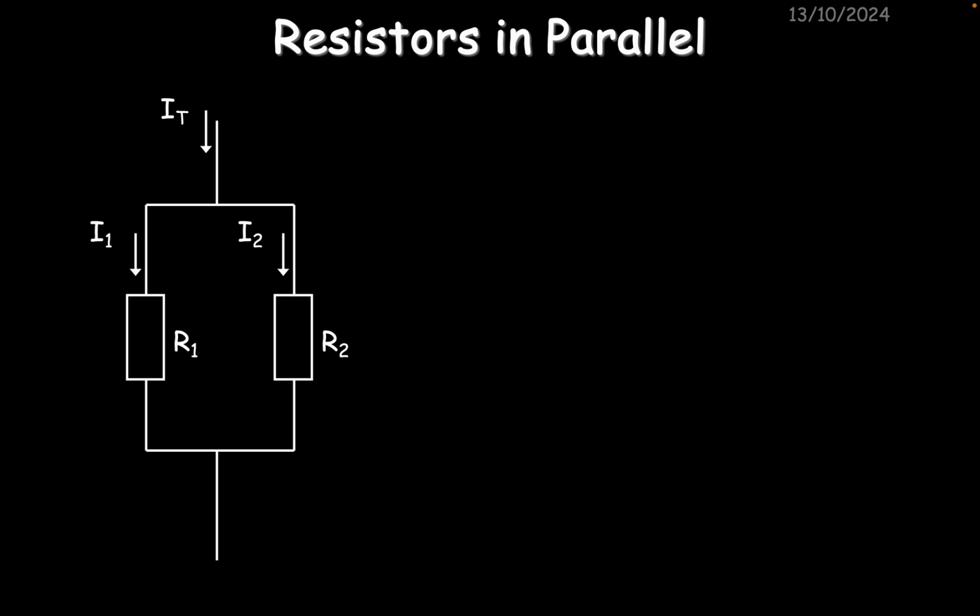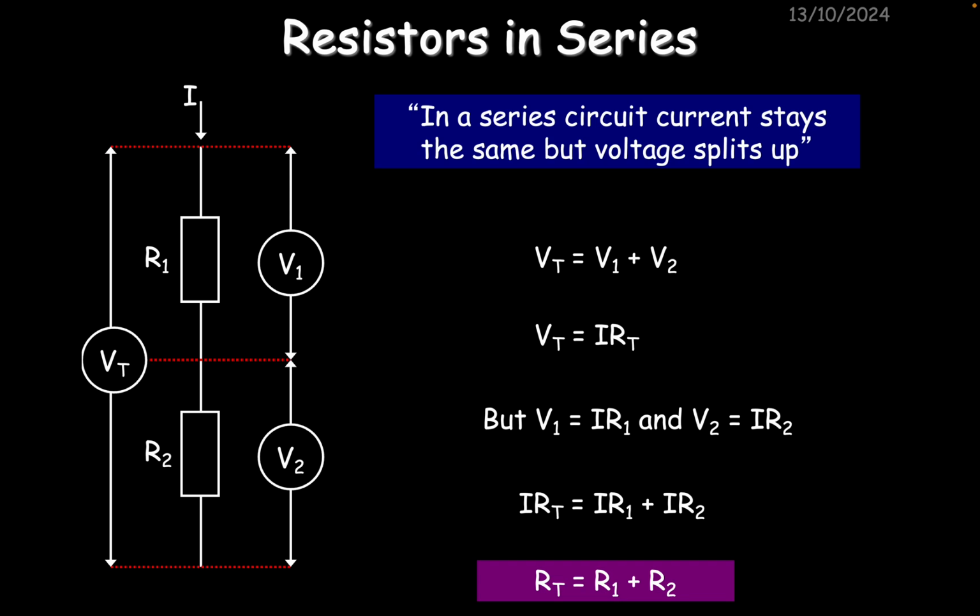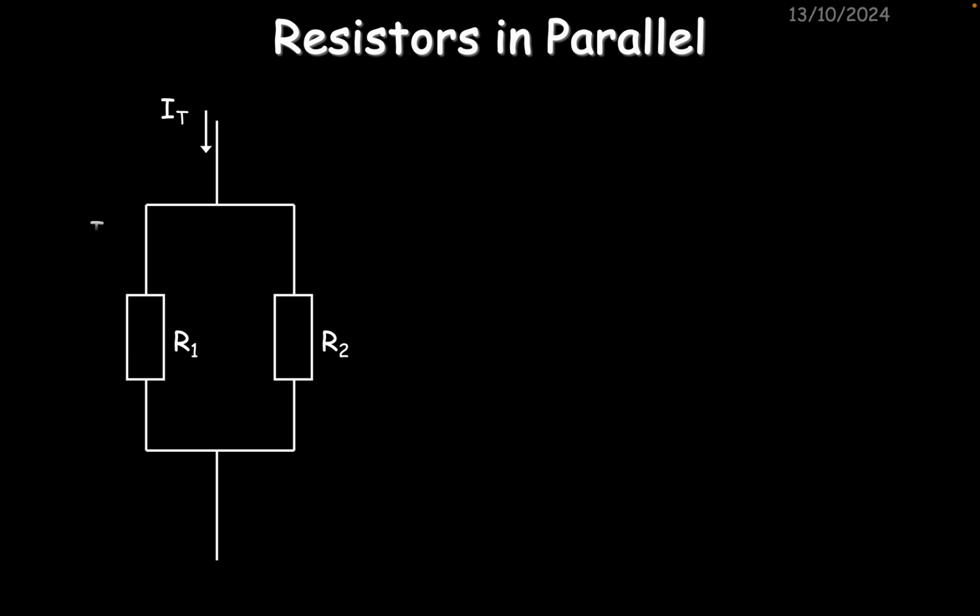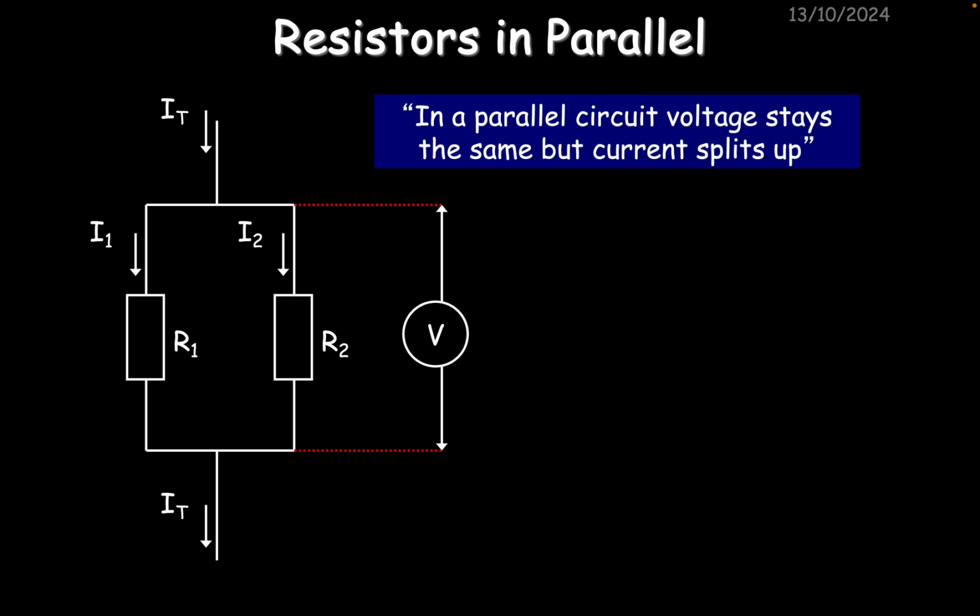So adding resistors in parallel actually decreases the total resistance, unlike resistors in series, yeah, from the last slide, where you add resistors in series, you increase the total resistance. In parallel, the more paths you have, the more you decrease the resistance. Okay? All right, so the voltage across the two resistors, because they're in parallel, must be the same. Yeah? So I'll let you read that.